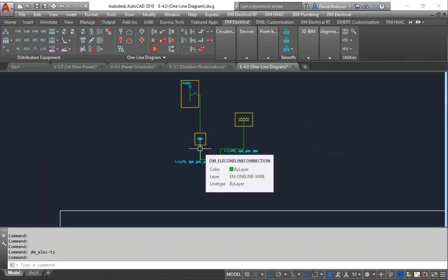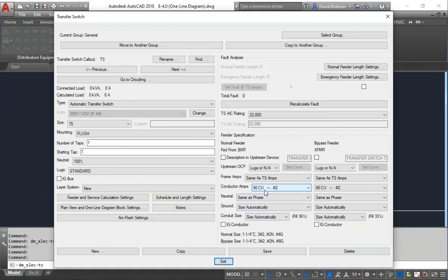Again, those are both number 8, so you expect it to be the same. But he has upsized the conductor wires. So this is a 70 amp transfer switch, but he is saying I'm upsizing my conductors to 90 amps. For service grounds, that doesn't matter on the ground size, so you just get the number 8 like you expect.